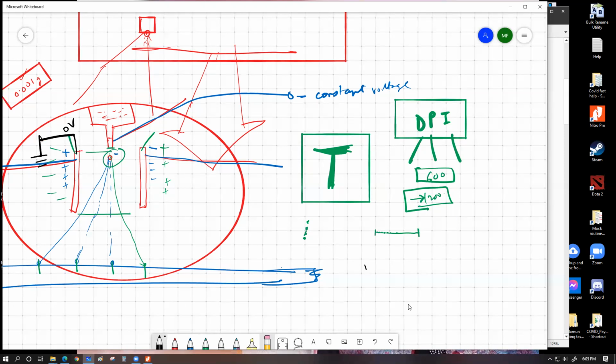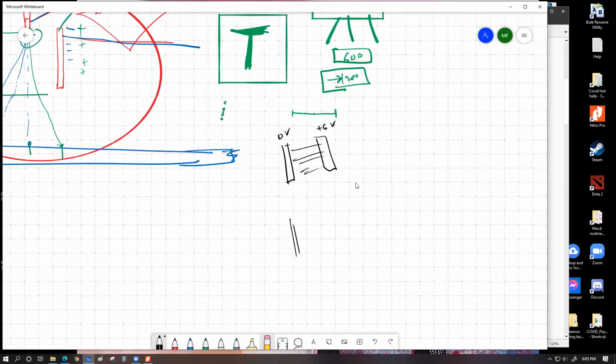What I want you to understand is this: if you have two plates facing each other at a single distance, one at 0 volt and the other at +6 volt, compare the electric field strength you get there to another case where one plate is at -6 volt and an equidistant plate is at +6 volt. You can see that the voltage difference is 12 volt. So the field is going to be even more concentrated, right? Yes, sir. It's going to be a much stronger field. So the benefit is that this helps you make more bend on the two sides.